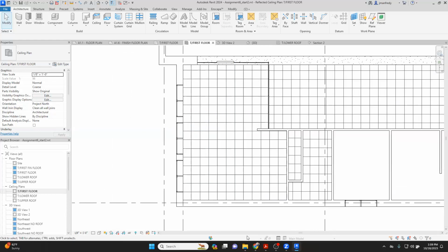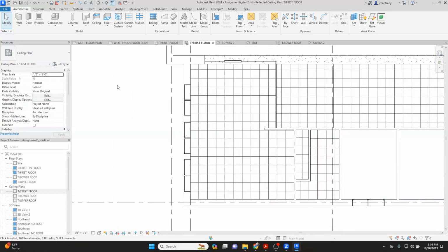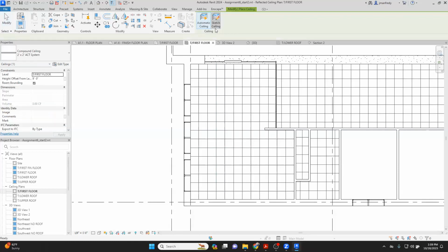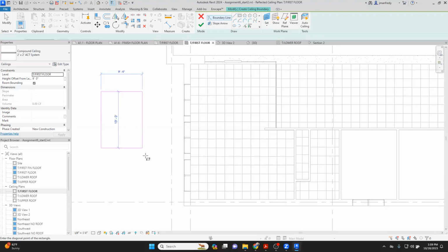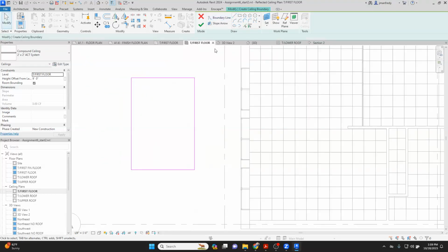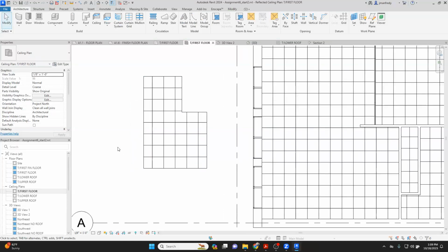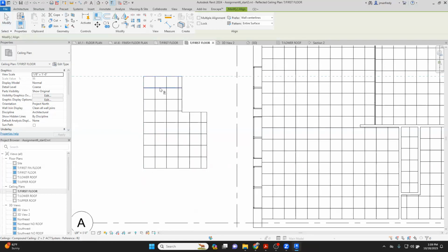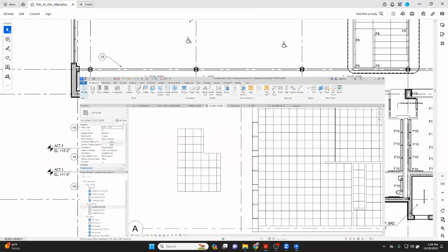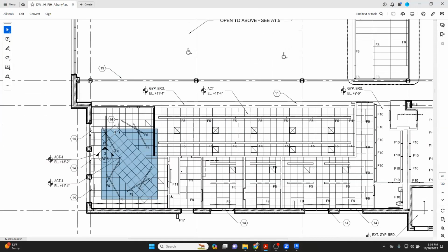Well, another ceiling here that's rotated 45 degrees. You can draw this using the sketch command, and I can draw any shape here. I'm just sketching it out. You can draw any shape with ceilings and accept it. And there's your ceiling. Now, I don't know if that's right, but I want to align this to make sure the edges are exactly 2 feet. And I can look at my design and copy it, right? This thing has 3 squares across the top. Each of these squares is 2 feet. So that is 6 feet. So you can see exactly how big this ceiling is by looking at the squares.